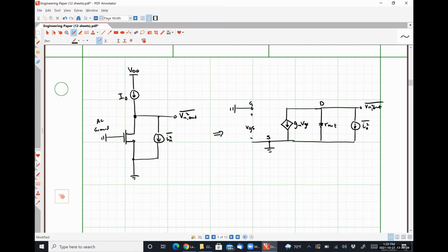All right. So one thing here that I'm going to mention, I have arbitrarily chosen the direction of our noise current to be down. It's a random process and we're going to wind up squaring things anyway. So the direction literally doesn't matter at all. Okay. So I'm going to call my output voltage always positive because we understand that it's a statistical distribution and it's just as likely to be positive as it is negative and all that kind of good stuff. So effectively, we get to play a little bit fast and loose with signs here.